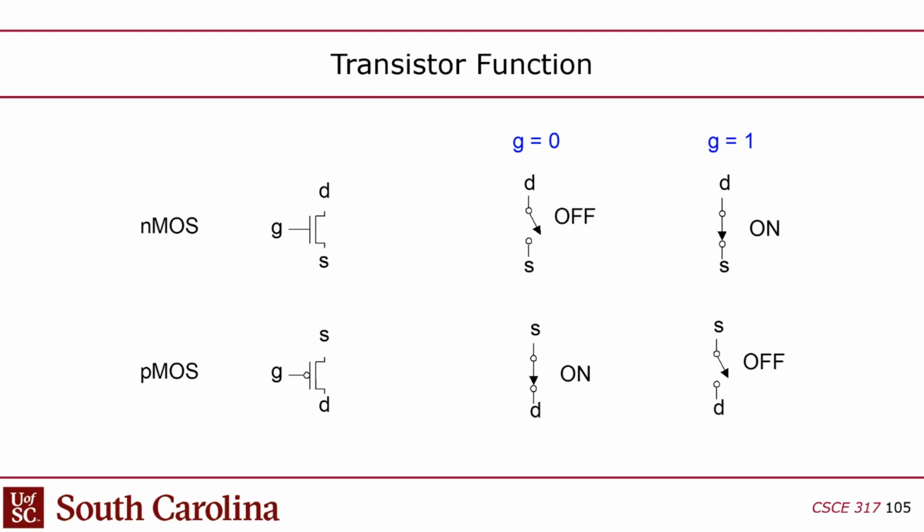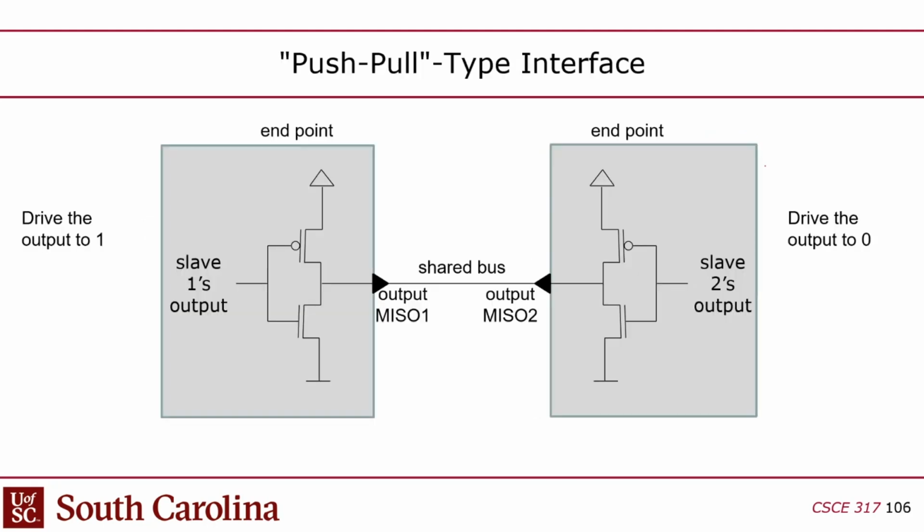So that's the transistors, and then normally a driver circuit like one on SPI is essentially just an inverter. A CMOS inverter, but a big CMOS inverter. These transistors have to be made large to minimize the on resistance so they can drive a big capacitive load, which would be an external wire, right? Because this external wire is going to be a lot of metal. It's going to have to charge up and discharge. So a push-pull driver is essentially a big CMOS gate.